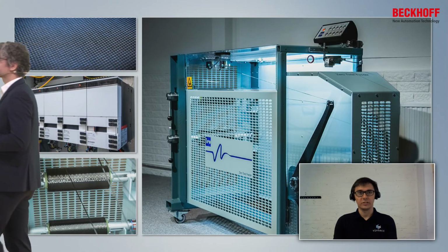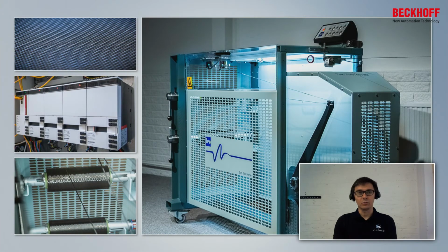Yes, for this project, the drives were very important. So we wanted to achieve very high performance on the control loops. The Beckhoff drives nicely integrate with TwinCAT, and you can add them in the drive manager, where you can see a visual representation of the control loops inside the drive, so torque control, velocity control, and position control. And you can tune the control loops whilst running. So that helped us accelerate developing the system and achieving the right performance.